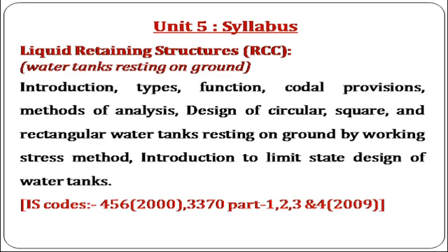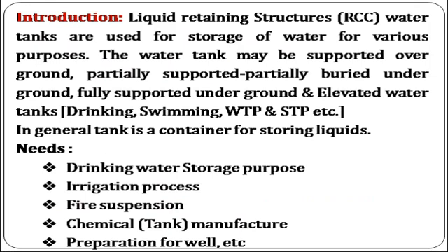We started in the previous lecture with the syllabus content of liquid retaining structures. This is the syllabus content and the different codes required for it, mainly IS 3370 Parts 1, 2, 3 and 4, required for the design or study of liquid retaining structures or water tanks resting on the ground.